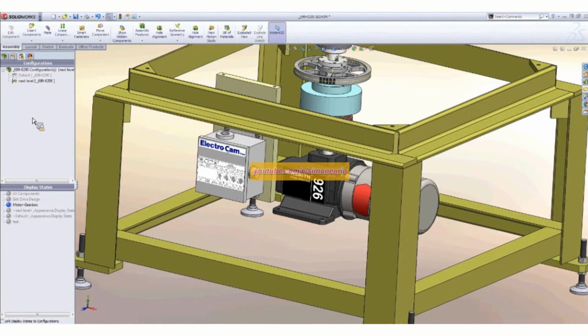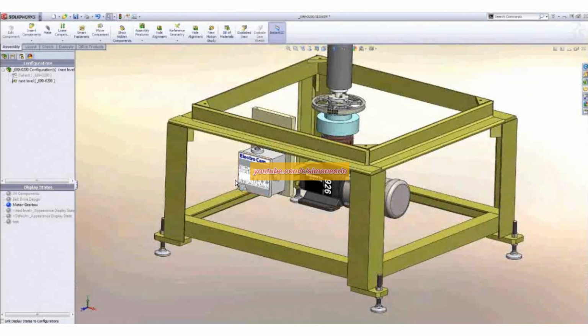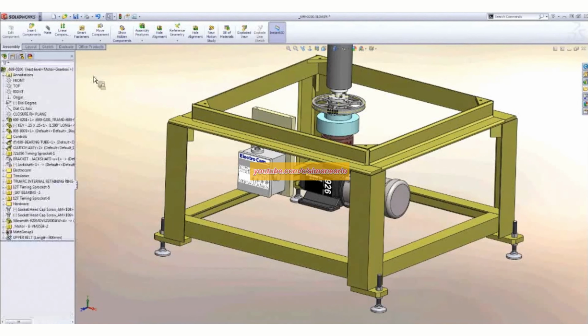And then in drawings, if you use your display states, that in a sense could be faster than bringing in, say, a default and then hiding components. Is that faster? Instead of hiding components individually on the drawing, yeah, it should be faster. Would it be less memory also? Take less space, I guess. It might be a little less just because the display information isn't there, but it's really only going to be less memory if you choose not to load the hidden components into RAM.